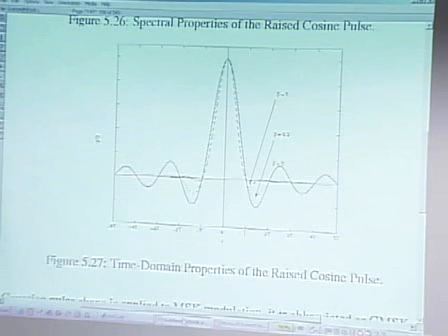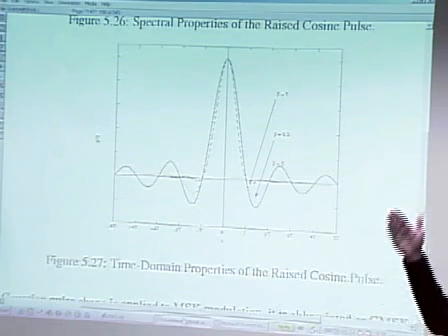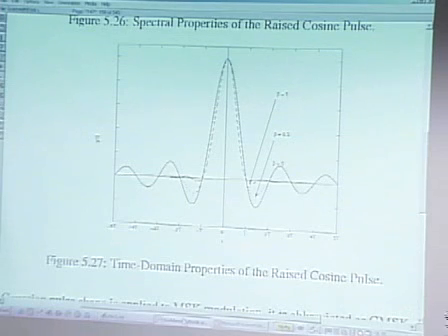So you truncate it in the time domain. What does that do to the frequency domain? It actually reshapes it a little bit. An easy way of truncating something is to window it, right? If you want to truncate a signal that is infinite, you can just multiply by a rectangle, by a window, and that way you can truncate it. That means you convolve its frequency shape with something else. So actually, that creates some ripples.